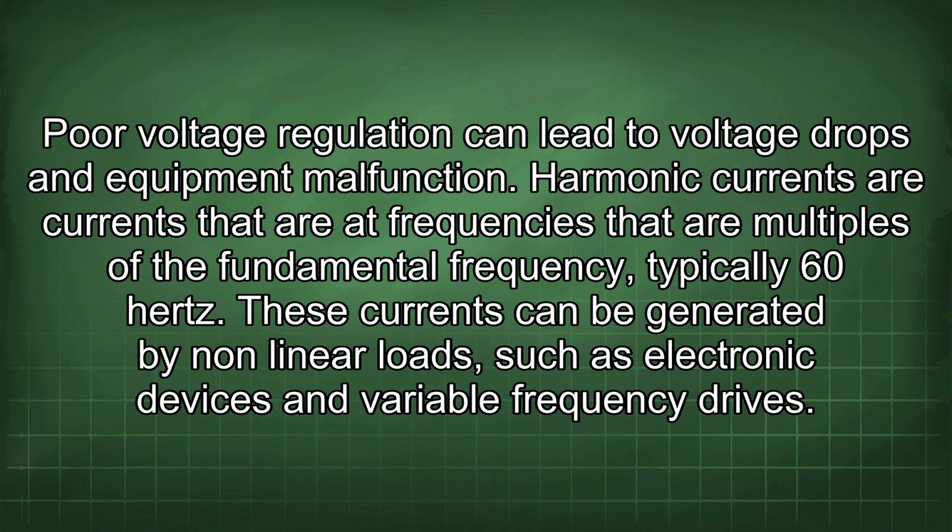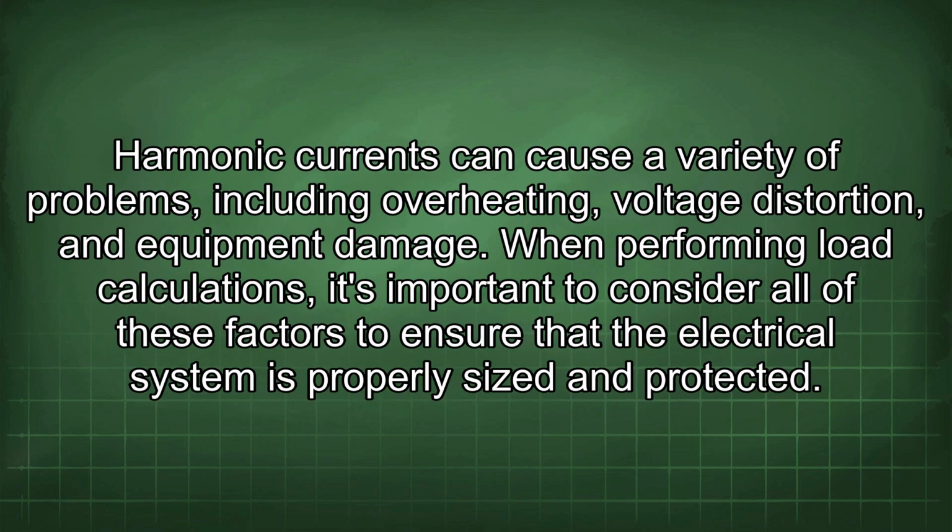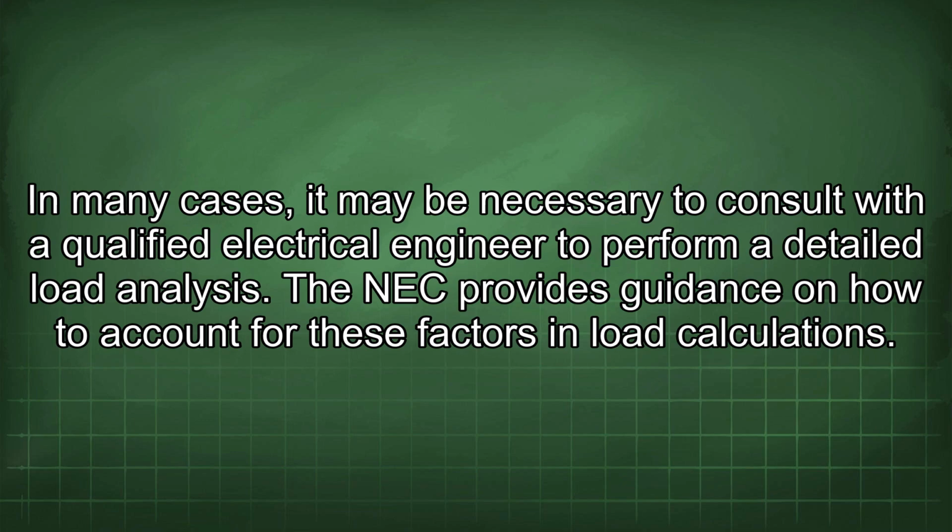Harmonic currents are currents that are at frequencies that are multiples of the fundamental frequency, typically 60 Hz. These currents can be generated by nonlinear loads such as electronic devices and variable frequency drives. Harmonic currents can cause a variety of problems, including overheating, voltage distortion, and equipment damage. When performing load calculations, it's important to consider all of these factors to ensure that the electrical system is properly sized and protected. In many cases, it may be necessary to consult with a qualified electrical engineer to perform a